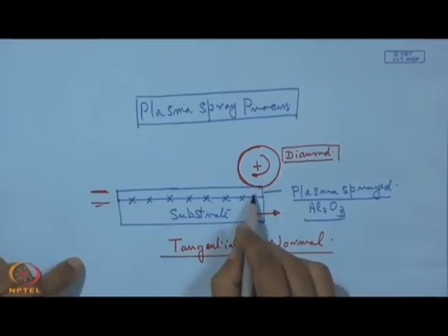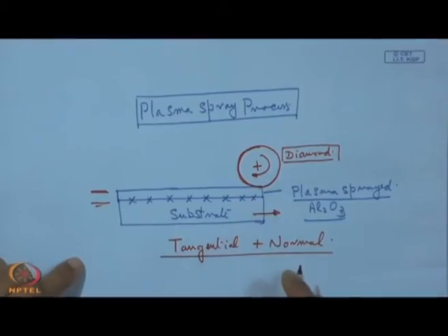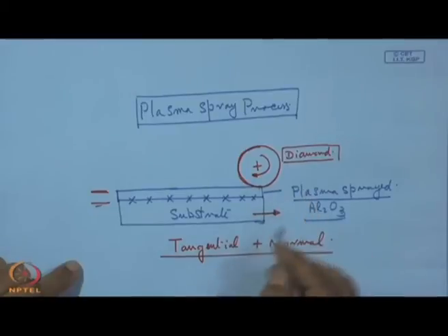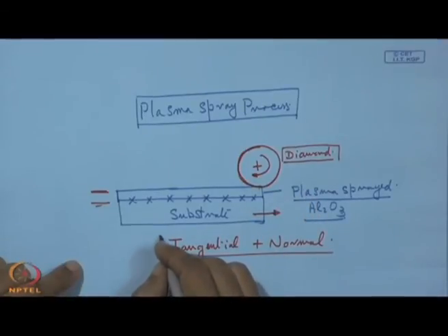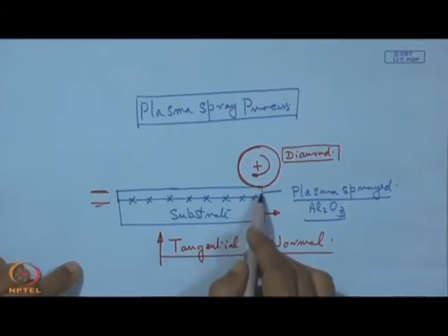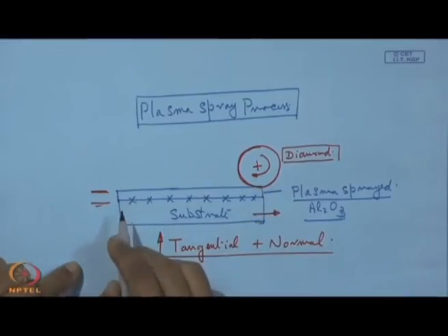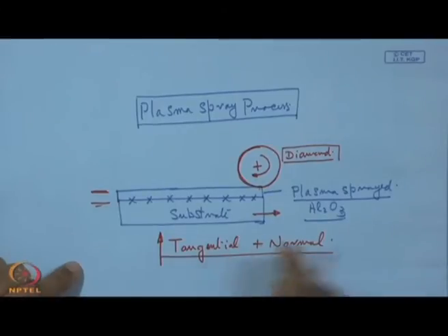So, depending upon this adhesion, quality of adhesion, the retention, what can be done? Gradually the depth of cut can be increased, and as a result of that, what is going to happen? This tangential force will go up. Now, if we find that the whole layer can be removed by gradual grinding without having any interface failure, then we can record a particular force, and from that we can say up to this point.